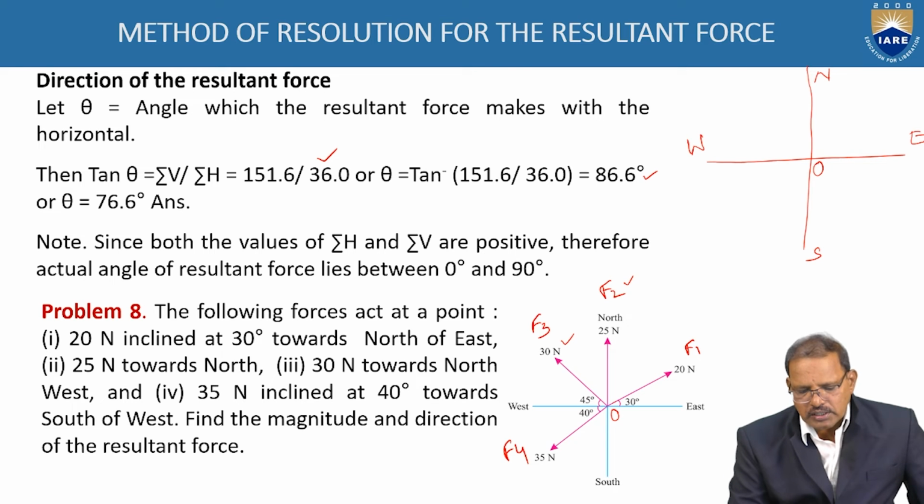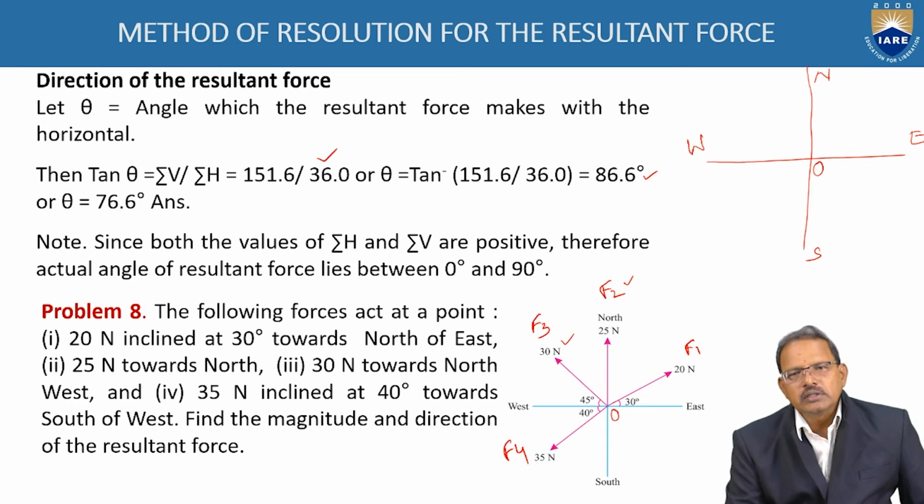Now in order to find the resultant as well as the magnitude of the resultant of the F1, F2, F3 and F4 forces, first resolve the forces into rectangular components. The first force can be resolved, here O is the point where it is acting, first into a horizontal component and a vertical component as shown in the figure.